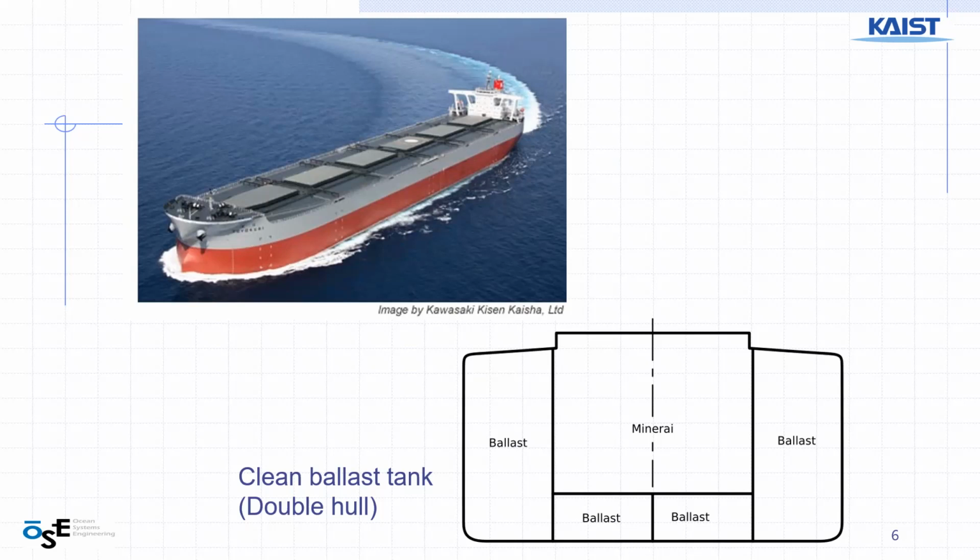But in the sea, an empty ship is very shallow, has a shallow draft. Draft means submerged depth. Say when the ship is full of cargo, the draft is about say 70% of the depth, right? Up to freeboard. But if the ship is empty of cargo and all the tanks are empty, the draft can be very low, say 10%. Then what happens? The motion of the ship is very dangerous because the waves are coming, wind is coming, and the shape above the water is higher and bigger, so the wind is blowing more in fact.